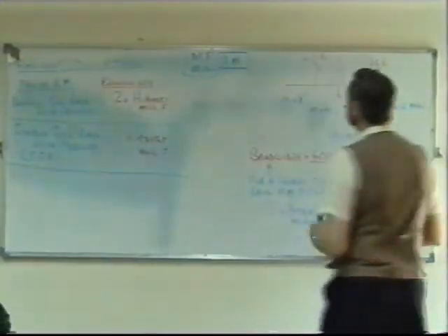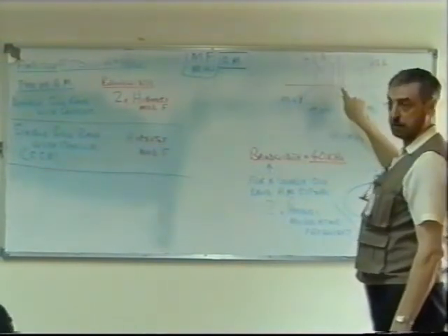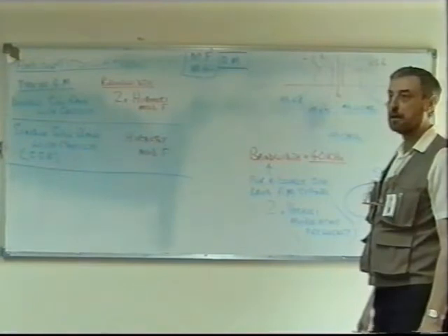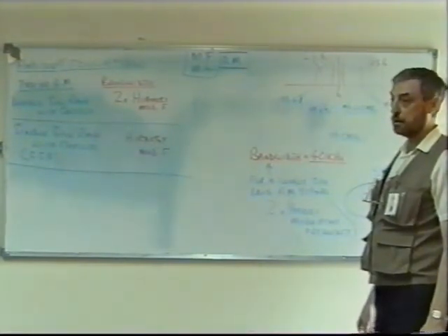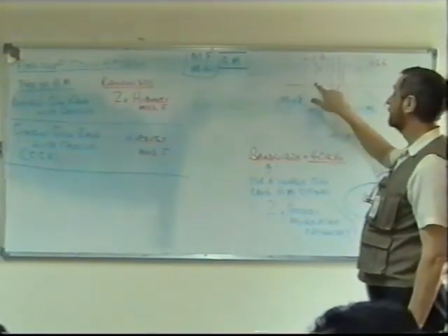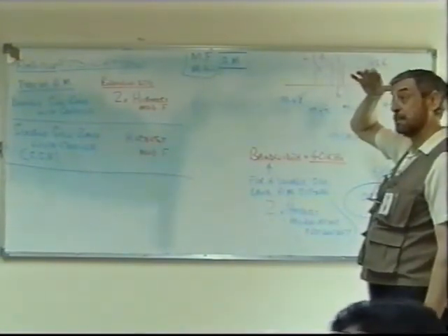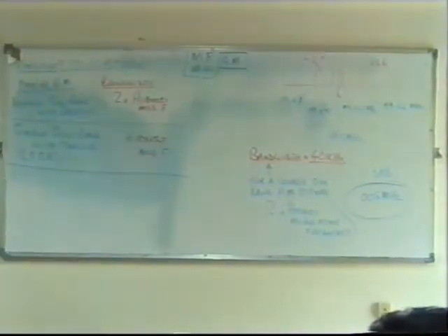Basically, in your transmitter, you generate this, and then you use a filter to select one of your bands. You choose a filter either for the upper or the lower sideband. You can choose either, and it will work. Is there any difference between choosing one or the other?